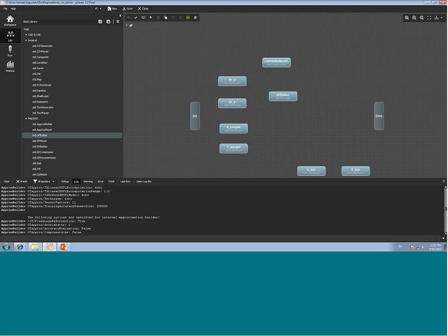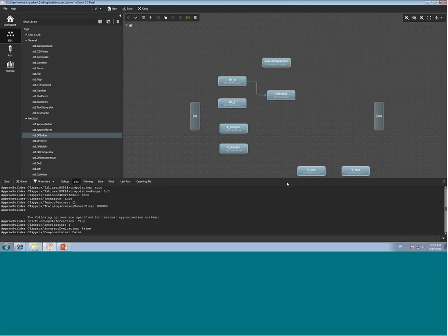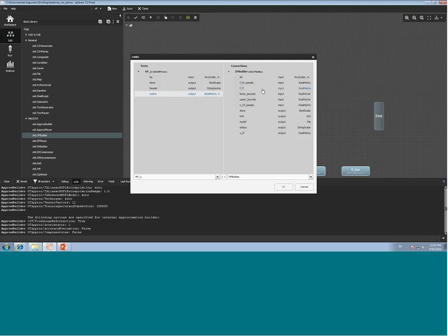Now pass the high fidelity data to the data fusion builder block. X data must be connected to the X high fidelity sample port. The Y data must be connected to the F high fidelity sample.